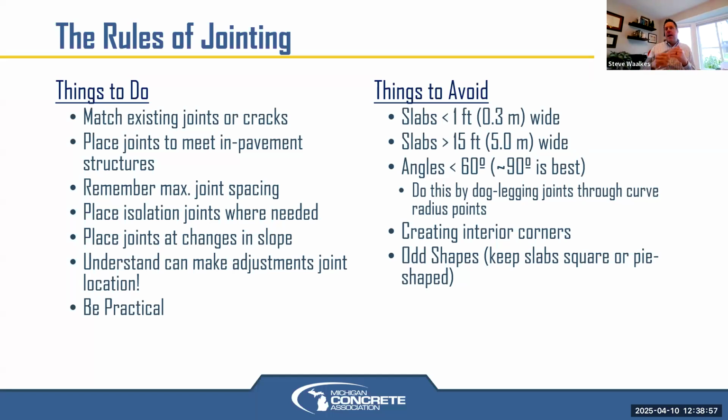For the 3-sided or 4-sided concrete precast box culverts, generally they have an adequate amount of ag base over top of them. They're usually not being used as a bridge deck over top, although in low clearance situations, maybe they would be, or some unique situations. But in those, generally it is not necessary. The joints don't have to line up over top of a box culvert.